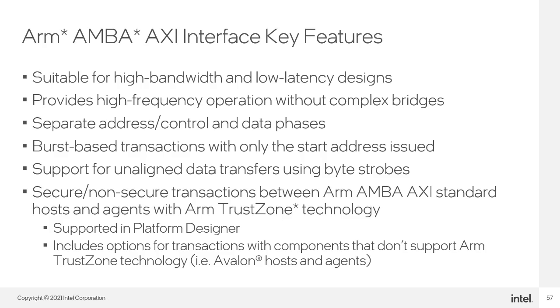Finally, the standard supports the idea of secure transactions where only approved hosts and agents can communicate with each other. Components that are not deemed secure cannot communicate with secure components. This is ARM's TrustZone technology. Platform Designer supports TrustZone and includes options for how non-secure components, such as any component using an Avalon interface, will be able to interact with secure components.